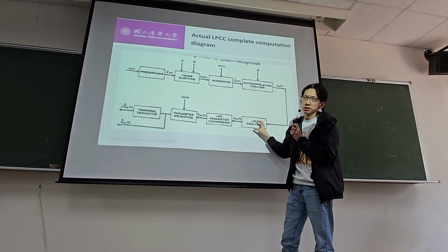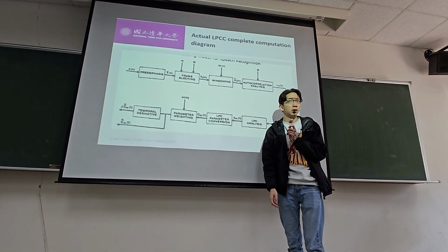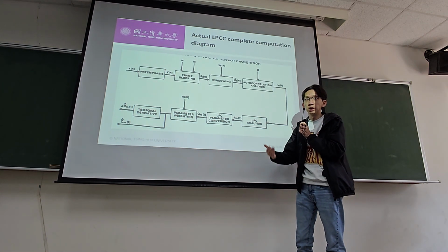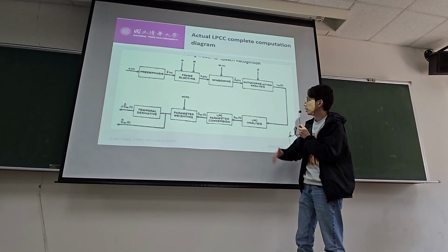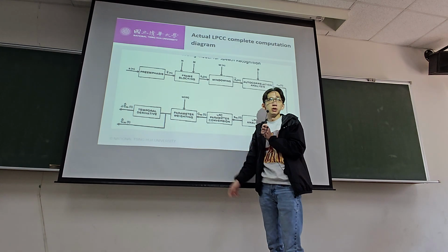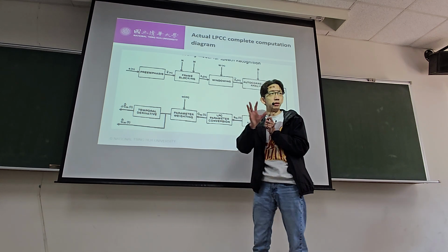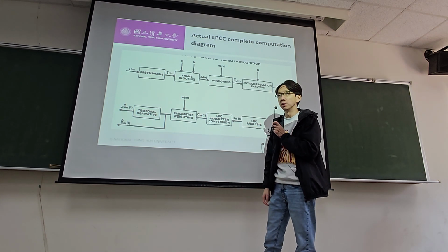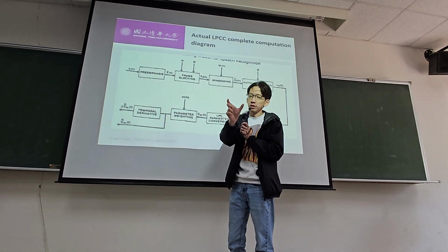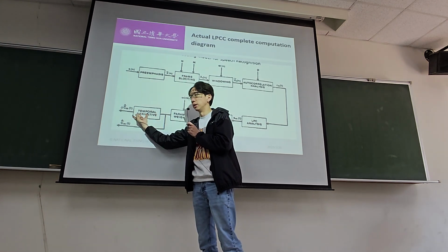Okay, the LPC analysis, inside of that LPC analysis, we know there are two particular methodologies to compute the alpha coefficient, right? So if we use autocorrelation analysis, we just need to decide how many p order you want to look into, how many past samples you want to look into, and then you derive the alpha coefficient. And the LPC models can be converted to cepstral coefficients, okay, through this inverse Z transform on the system function of the LPC model. Then you pick the portions of the cepstral coefficients you want. That part we call parameter weighting, and then eventually also take temporal derivatives.